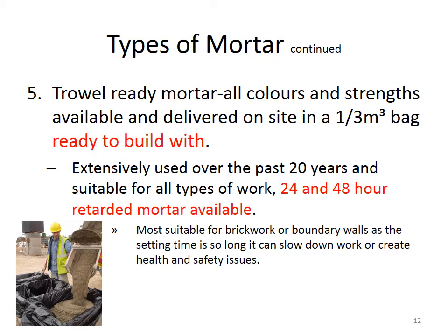So in other words, when it gets delivered onto site, you have up to 24 or 48 hours in order to actually use the mortar. The good thing about this is that it's not going off really quickly, so you don't have to be mixing on site. But the bad thing is that you can't build very high with it, and in damp conditions it takes even longer to start stiffening, starts getting initial hardness, and for strength as well. It takes a while to get its full strength.